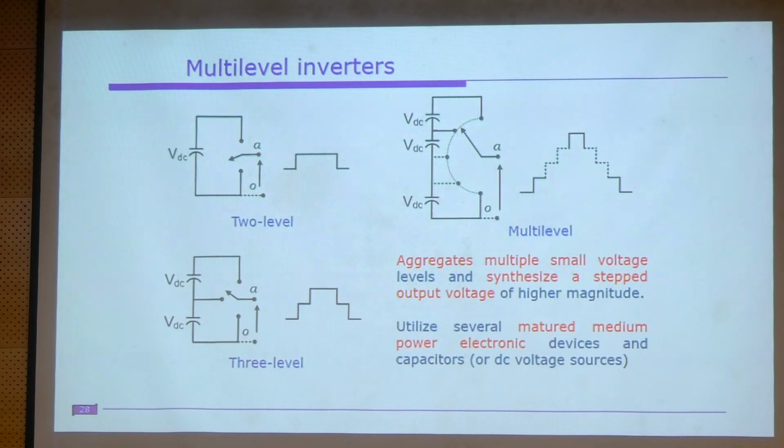So this is how the multi-level inverter concept is seen. You might have studied this one. If you observe the first one, you have one DC source, and there are 2 points. This is the point A and this point is 0. One switch is toggling between A and 0. Let us assume we are measuring the voltage across VA and 0, right.